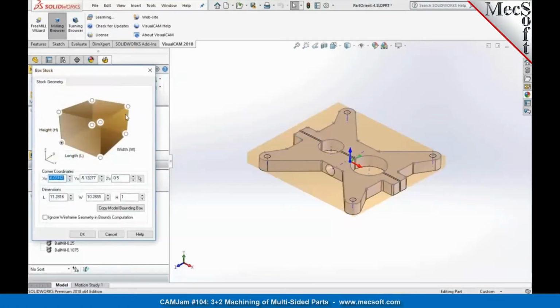stock. So as you define your stock geometry, you will notice that the stock extents that you see here are based off the machine tool coordinate system orientation. So the length of the stock is 10.5 inches on the machine tool coordinate system of the x-axis that you defined. The width and the height or the thickness is 1 inch.